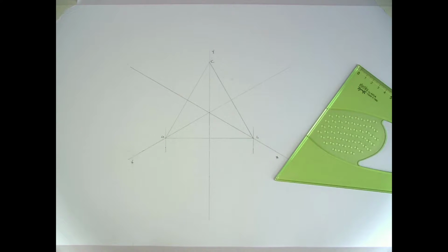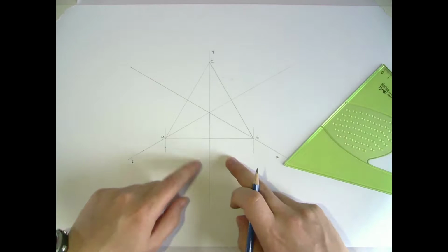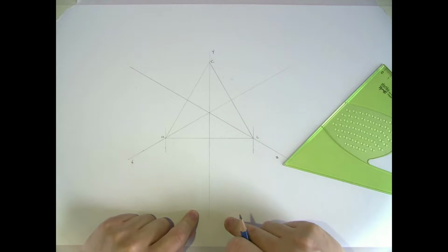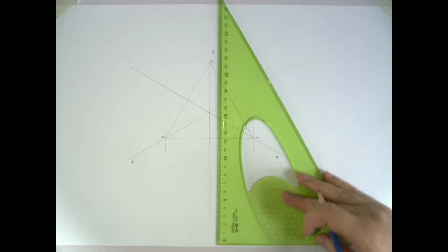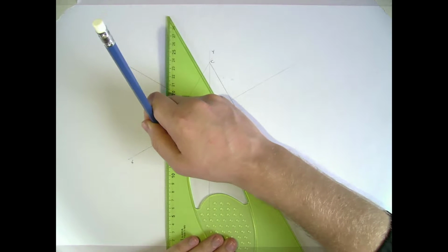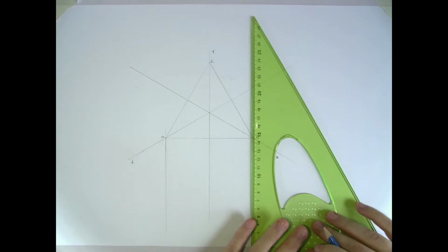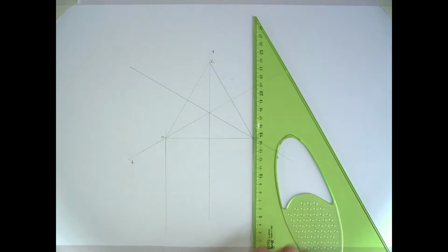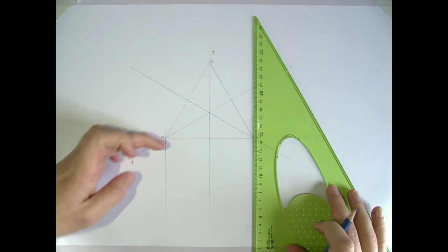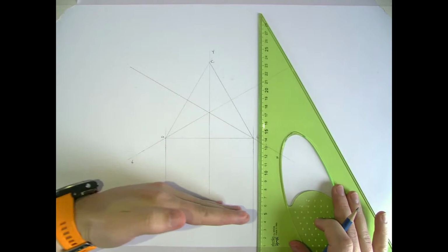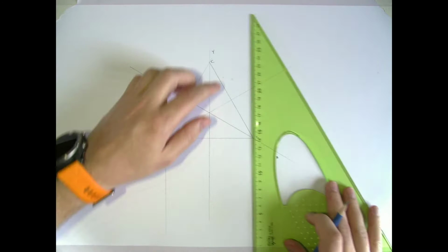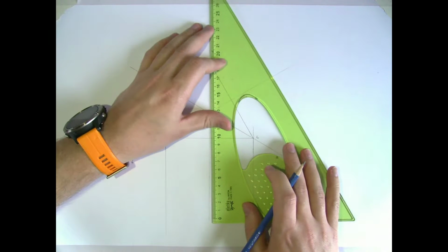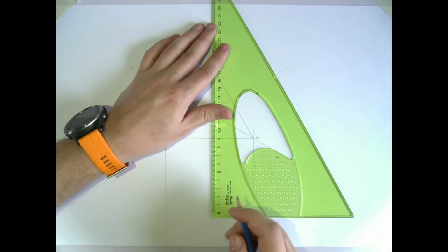What I'm going to do is start by drawing the plan, and the plan is going to be positioned down here. To do this, we're going to take points A and B and project them down parallel to the Y-axis. We need to draw a line that's parallel to AB, and I'm going to come down about 90 millimeters from where I positioned it.